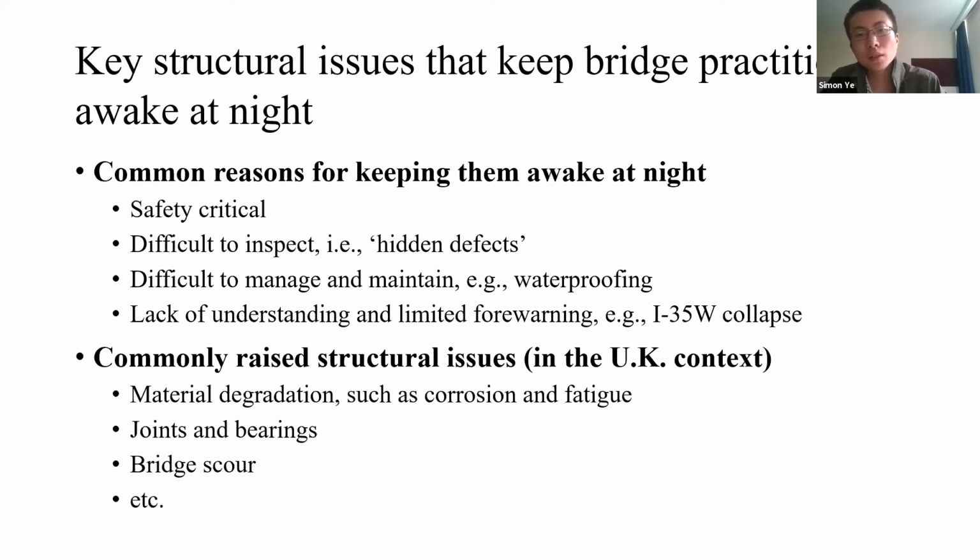So the commonly raised structural issues in the UK context. The first one, the top one, is material degradation, such as corrosion and fatigue. The next one is joints and bearings, and third one is bridge scour, and there are also a lot of other issues.